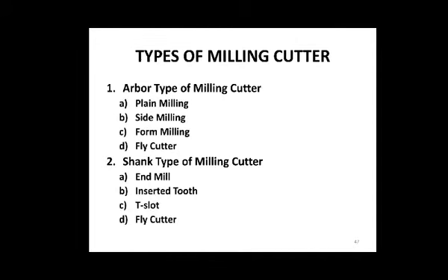Ceramic inserts are typically used in high speed machining with high production. Diamond inserts are typically used on products that require tight tolerances, typically consisting of high surface qualities, that is, in non-ferrous or non-metallic materials.